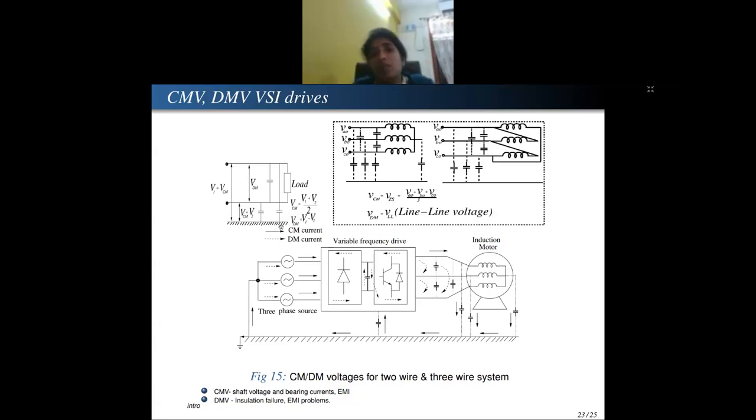In any electrical system, different parts would be operating at different potentials unknowingly, because there are drops somewhere, there are added values, so automatically the wires will have some inductance, and then at different points the voltages will be different. So between these two points, say for example the top wire and the ground, the voltage will be different. Between this V1 and V2, the voltage would be different. So automatically, even if the wires are insulated and placed nearby, the parasitic capacitance will be present.